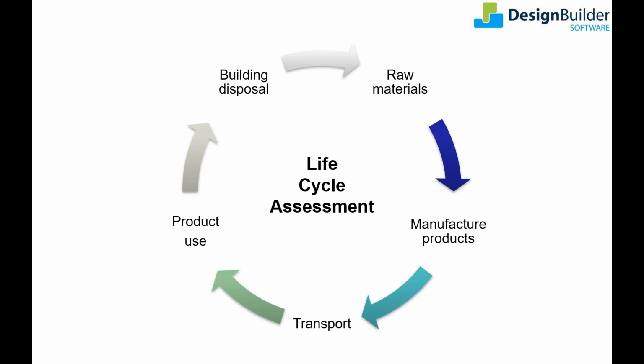In recent years, LCA has become much easier via tools like DesignBuilder and One Click LCA, with their libraries of embodied carbon data. So those early barriers have now largely been removed. Secondly, the performance of the building fabric, HVAC, lighting, etc. has improved dramatically in recent years. And that has made embodied carbon a much higher proportion of the overall carbon footprint of the building. Third,